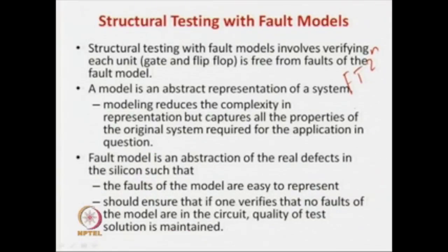So, the large number of input patterns we solved using structural testing. Then using the internal registers we solved the problem of the large number of pinouts. Initially with functional testing it was 2 to the power n; we used structural testing and brought it down to k; then we had large pinouts, which we solved using registers. So now we are in a position where we have a huge number of registers. This is our flow.